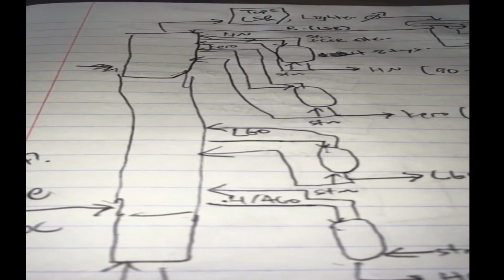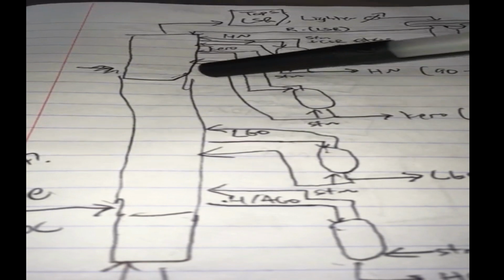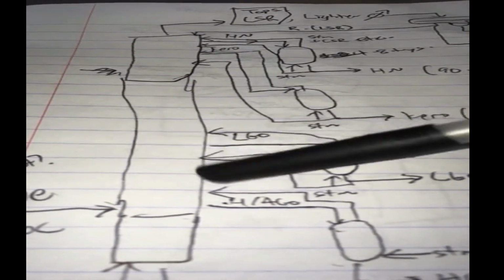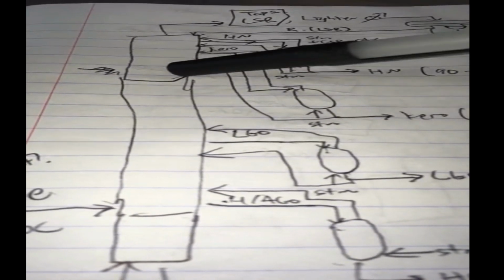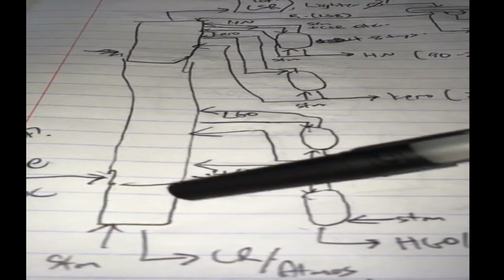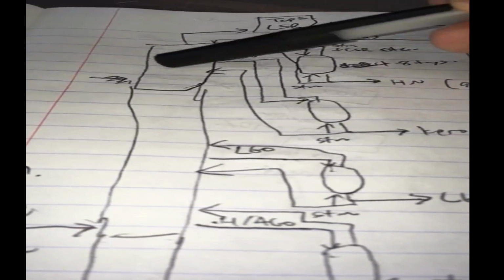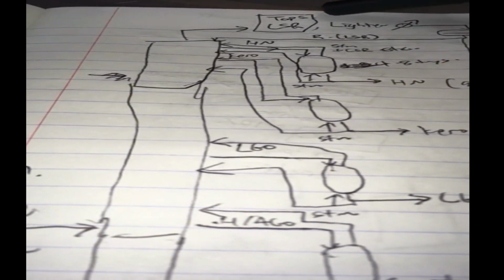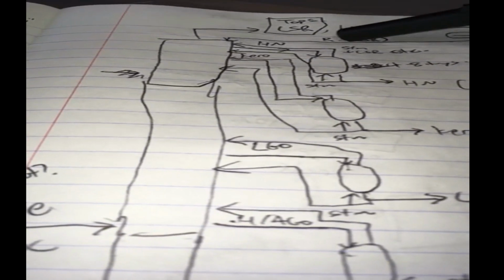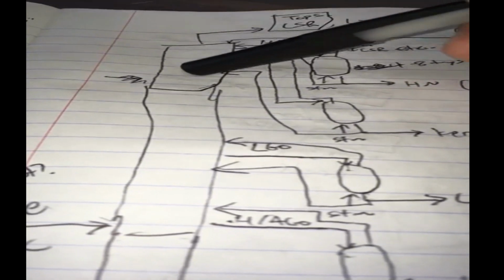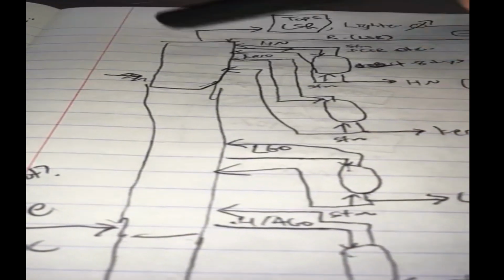Okay? That's a multiple reflux. So if I control this reflux ratio from the kerosene portion, I can control the amount of purity in my light gas oil, heavy atmospheric gas oil, or heavy gas oil, and I won't affect anything over here as much as compared to when I just control this light straight run and everything down will be affected.